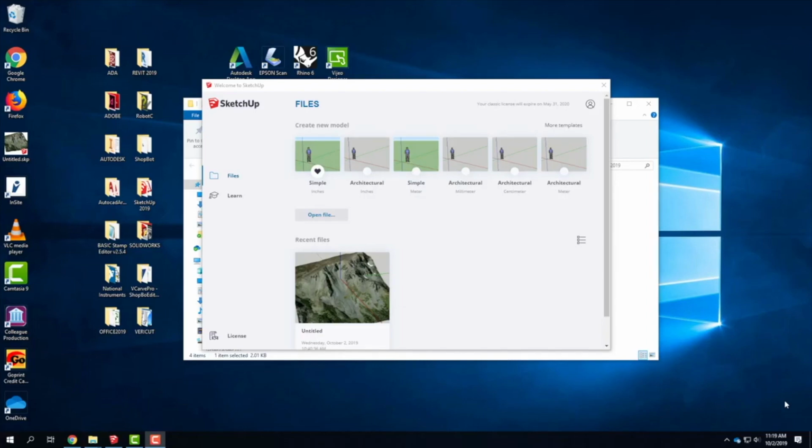So the first thing that we need is some kind of a source of the terrain information to begin with. You could have terrain information coming from a surveyor or from some model that pre-exists that was given to you as part of your design process. For our purposes, we're going to pick a piece of terrain and use the SketchUp Geolocation feature to get that piece of terrain. It's not the most accurate piece of terrain in the world, but it is a place to start, and it's something that everybody can pick from. So that tends to be a good thing.